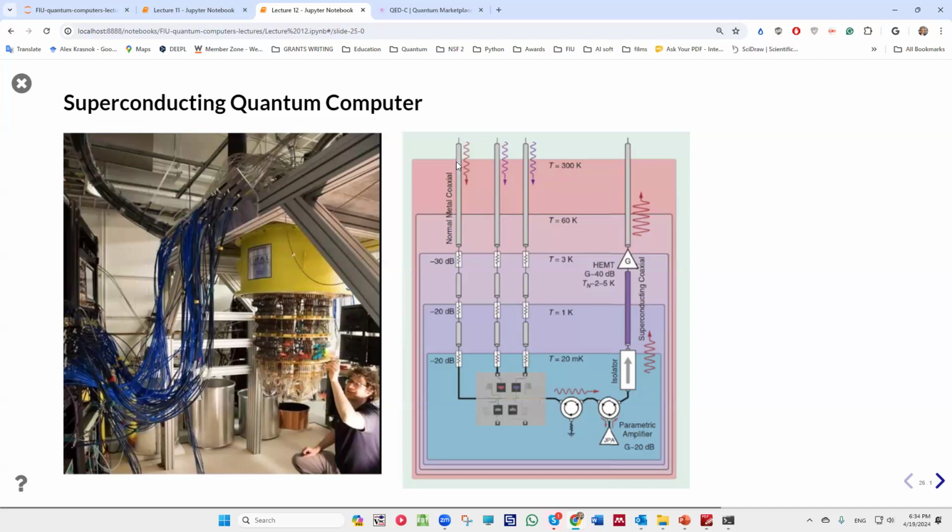The reason is that, in contrast to initiation pulses, the input pulses that come from room temperature and go to the chip, we can attenuate by a number of attenuators, like minus 30 dB, then minus 20 dB, minus another 20 dB. So the signal that comes to the chip is very, very weak. That's how we can reduce the level of noise that comes from room temperature.